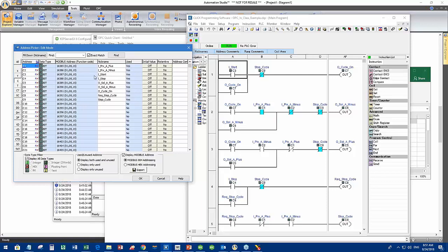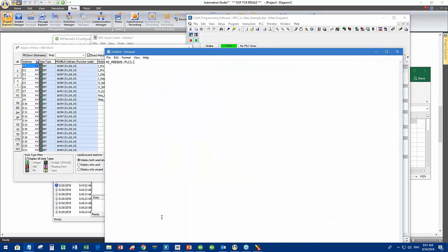So this is the address I'm talking about. I have to put in this line. So you do here, the format in Modbus has to start with a 0, and I write 16.385. Okay, so this is my address for the item.